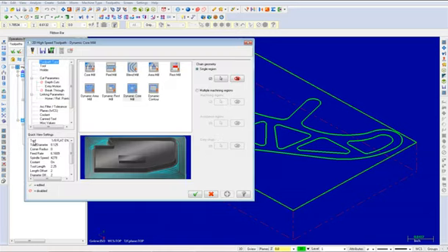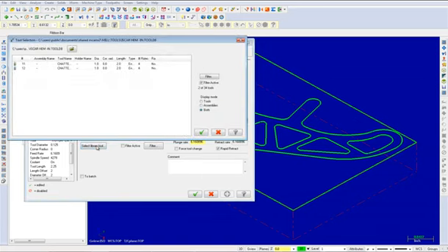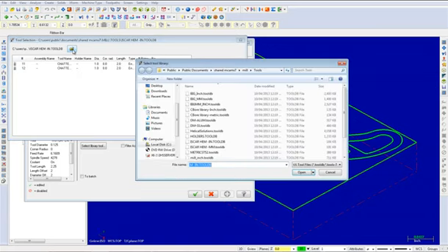In the Toolpath Type page, the Dynamic Core Mill will be selected. We will now choose a chatter-free 1-inch flat end mill from the library and set the tool parameters. From the Tree View list, choose Tool. Click on the Select Library Tool button. Click on the New Library button. Select the following and then choose the Open button.